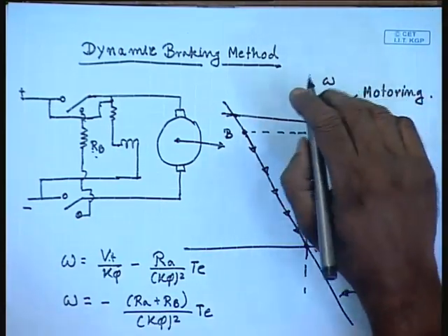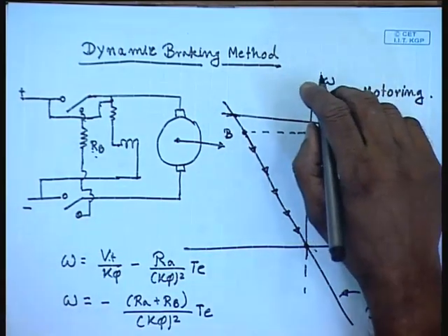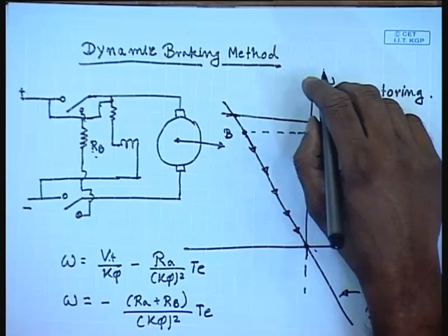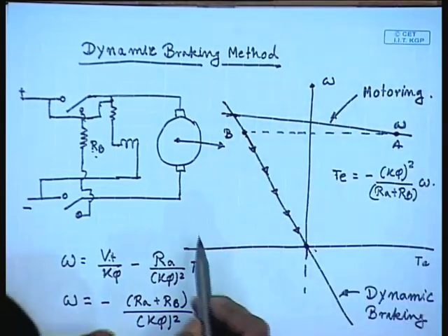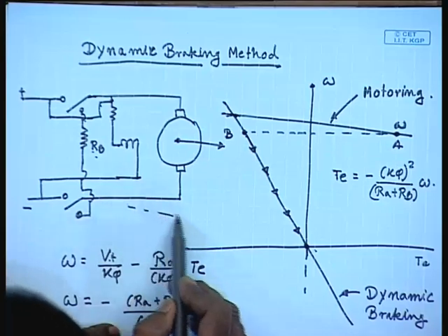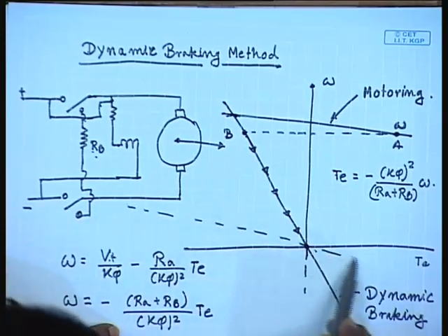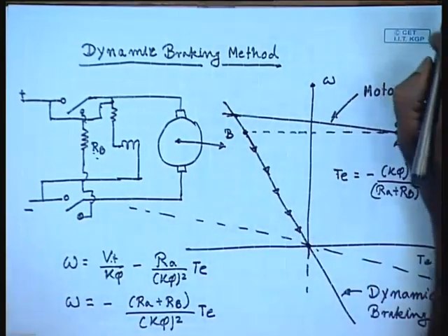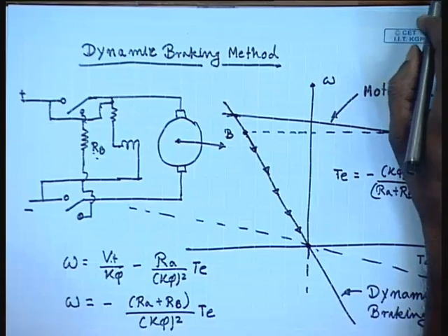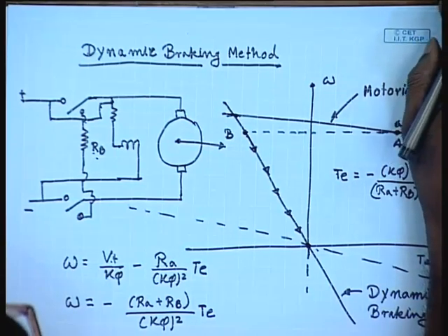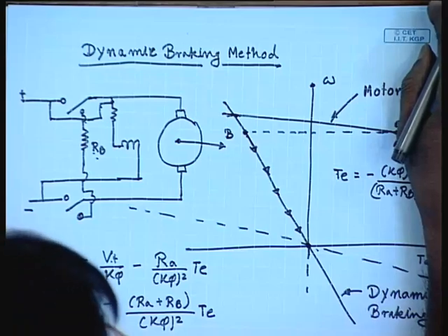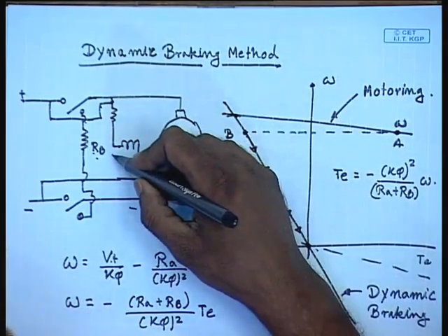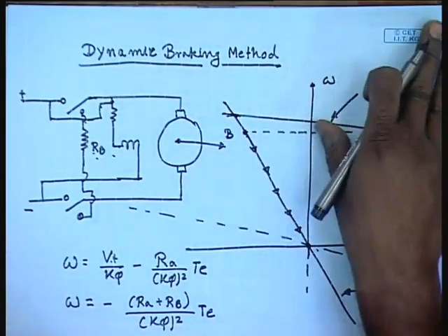It is important to add an additional braking resistance, because otherwise the current during braking can be very large, almost the starting current with direct online starting, which is not desirable. Therefore, additional braking resistance is normally included.